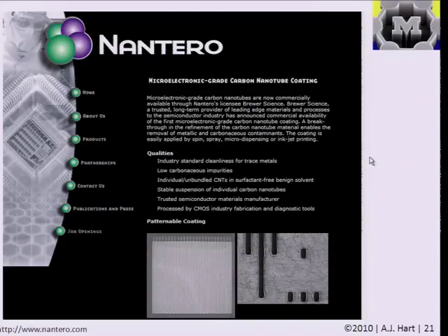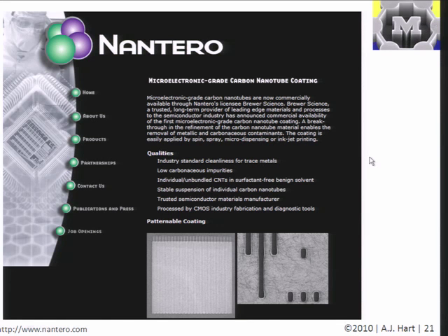And they've done all the pre-purification such that this material is now compatible with CMOS standards. So it's clean enough to go into a commercial clean room. And here are just some SEM images of devices that they've patterned taking from this film. So for example, spin coating this thin film, and then masking it with photoresist and doing plasma etching to define patches of the film that you wanted to keep and patches you wanted to throw away, and for example putting electrodes on the surface. And in fact, this is the type of material that this company is now using to make a memory based on thin films of nanotubes, just by actuating suspended ribbons of the nanotubes electrically.